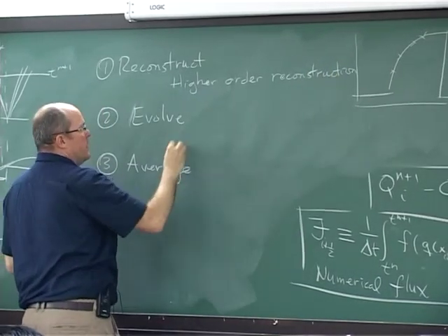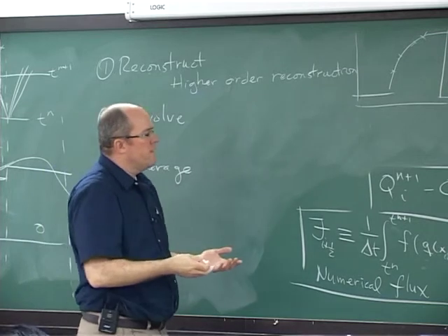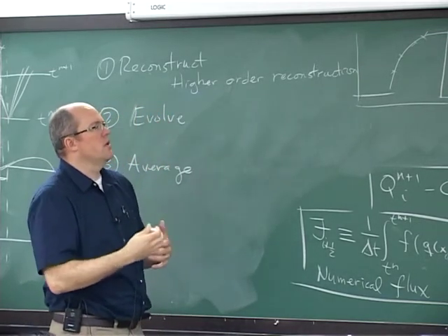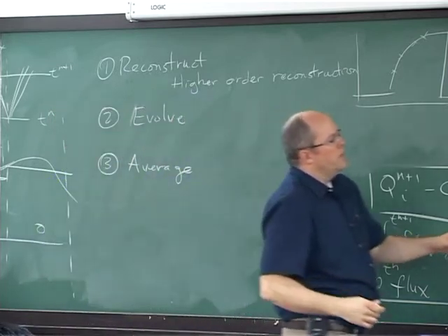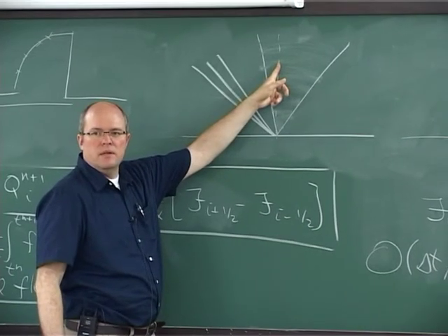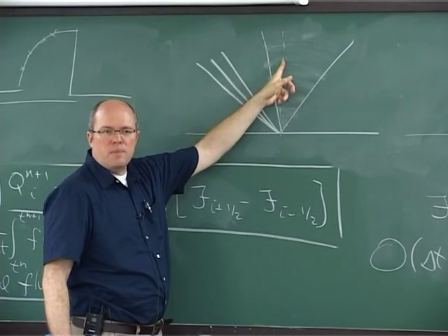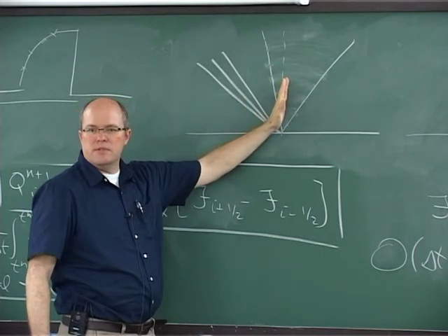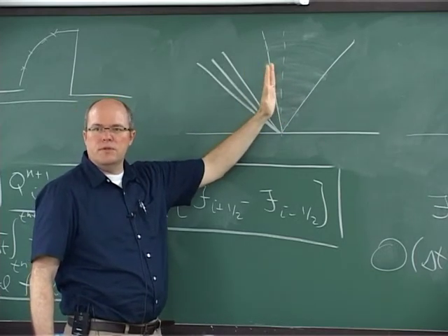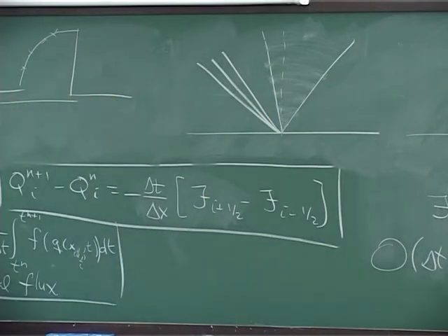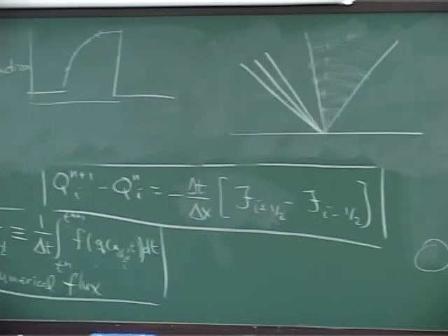And again, with the Riemann problem, it's expensive to solve, and we're using only one single point that comes out of it. And so maybe it's possible to approximate the solution, not find the full solution of the Riemann problem, but find an approximate solution. And that's the other thing we'll look at: using approximate Riemann solvers.